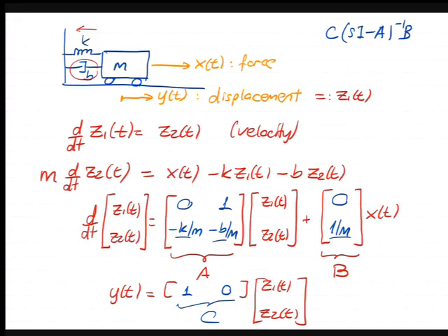Of course, they will depend on M, K, and B. Try to connect with your intuition about, if the damper is not there, B is 0, then you're likely going to see oscillations. Or if B is small, you're going to see oscillations. So you should check these conditions for complex poles and even resonance in terms of the values of K, B, and M, and try to build some intuition using that, okay? Especially if you're in an ME major.